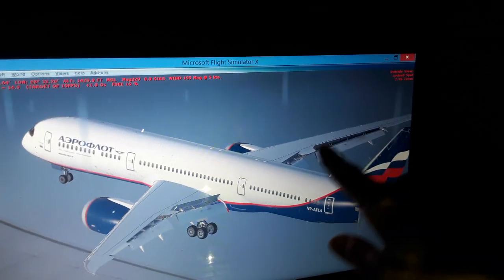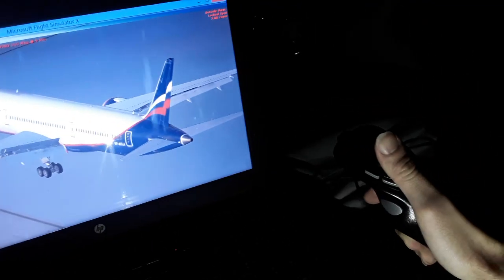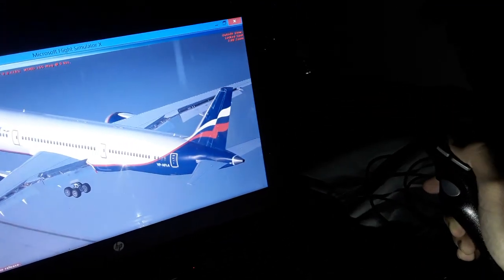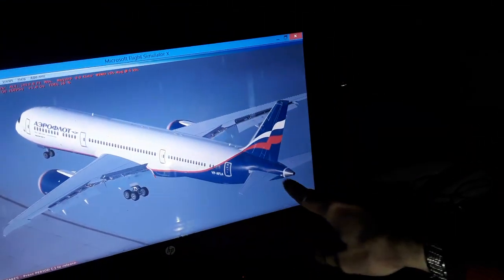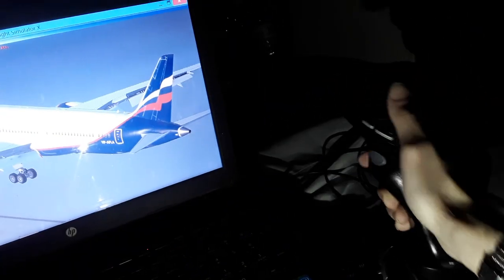So we have the deflection from the flight controls over here of the airflows. So you can climb and descend, you can make turns in the air, turns to the right, turns to the left, through around the longitudinal axis. You make the bank rolls. This is the longitudinal axis, transverse to the vertical. Around the vertical you make, using the rudder pedals, the yawing turns. Through around the lateral, from wingtip to wingtip, you have the pitch attitude. From the horizontal tail you climb, descend the aircraft like this.